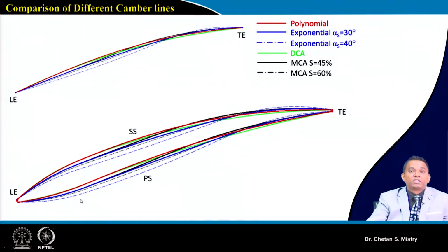Now with this, we are able to generate the airfoils, and after generating this airfoil, we will be managing our flow passage. By managing our flow passage, basically we are managing our shock structure. We are managing the placement of our normal shock, and that's how we are managing our diffusion within the flow passage.